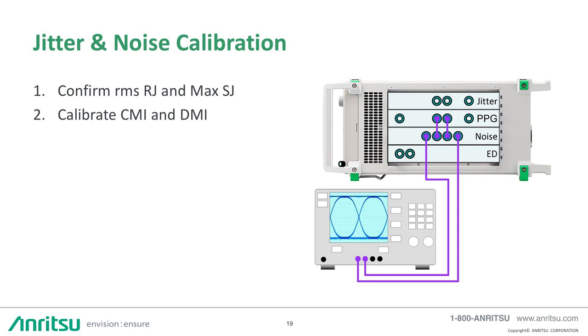Transmit sinusoidal differential mode and common mode interference with amplitudes of 5 to 30 millivolts at 2.1 gigahertz across the test board and to the oscilloscope. Since the channel has about 6 decibels loss at 2.1 gigahertz, the interference amplitude at the BERT pattern generator output will not be the same as that on the signal delivered to the compliance baseboard.